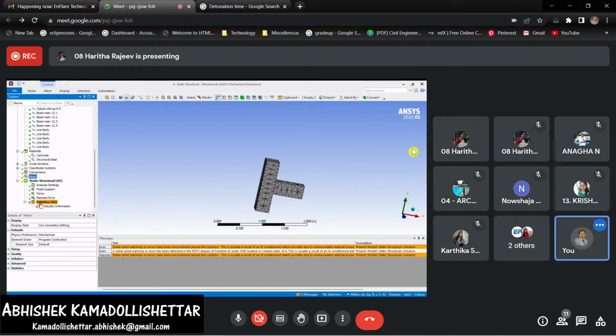Okay, fine. Then what I'm suggesting is in the mesh part, you reduce the size of the mesh, because I'm not feeling comfortable with the meshing as it is; the software will not solve it very easily. So go to the mesh and, instead of default, give some size.